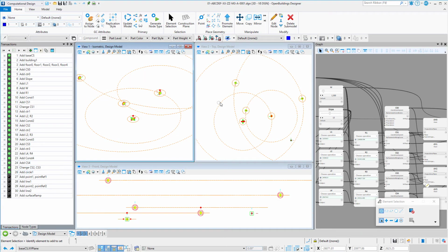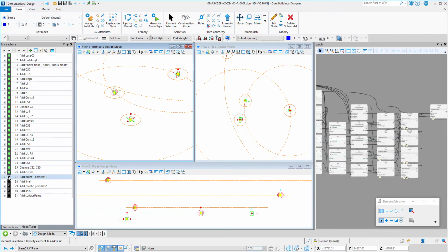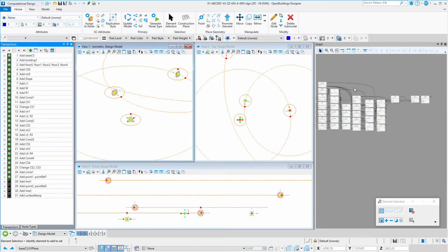So first I added a circle at each of the coordinate systems with the radius defined by the width variable. Next I needed to project a point from one coordinate system tangent to the next circle. I did this with the technique project at tangent to curve, and used a list of all the coordinate systems and circles to do all the points with one node.